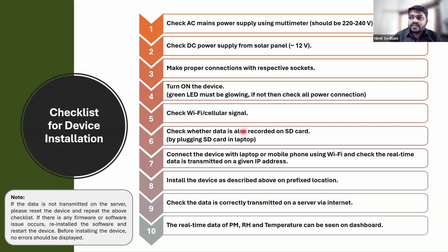Mostly you can see that people are saying that our low-cost sensor is capable of monitoring PM1, PM2.5, and PM10 also. Mostly they use a 660 nanometer wavelength based on Mie theory, and they calibrate those sensors to give accurate results for PM2.5, but not PM10 and PM1.